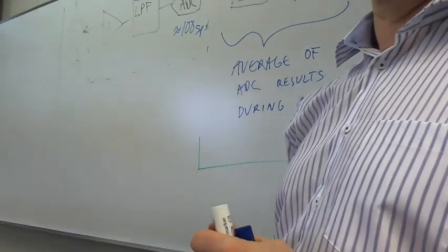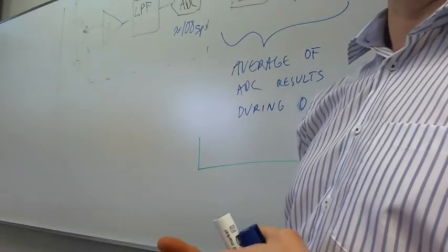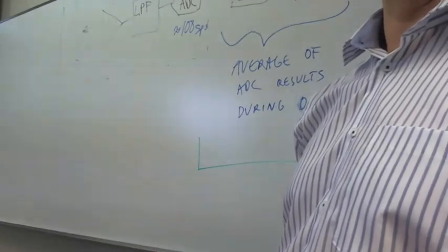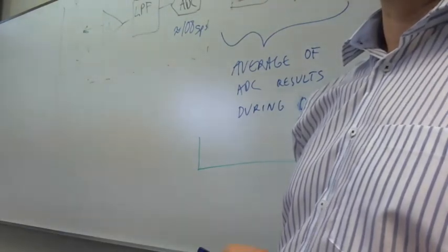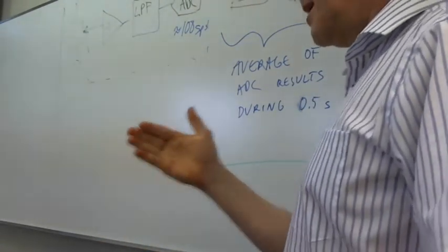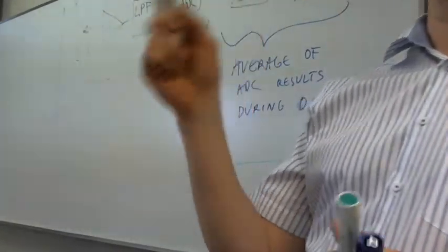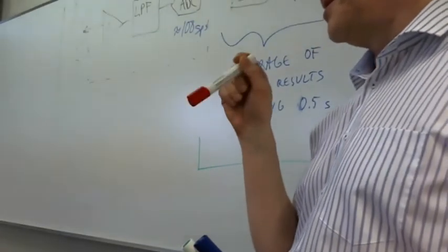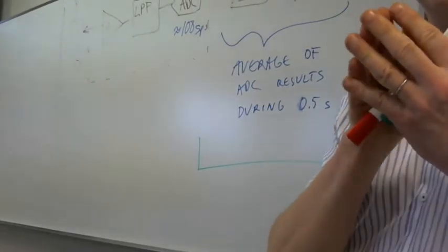This is a trick question. You get either 49, 50, or 51. Why? I'm quite sure that in some cases the timing varies because you are doing something else on your main loop when the interrupt comes. So you do not necessarily get exactly 50 samples for this half second time frame.